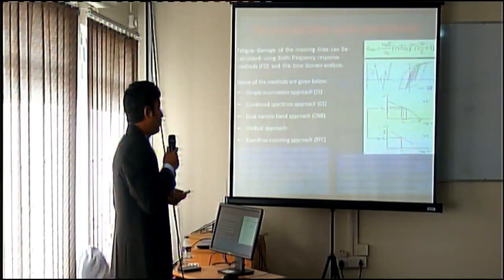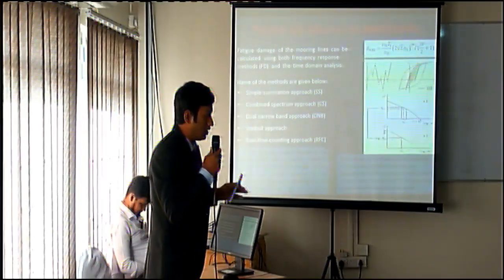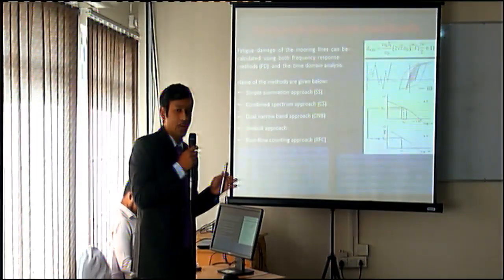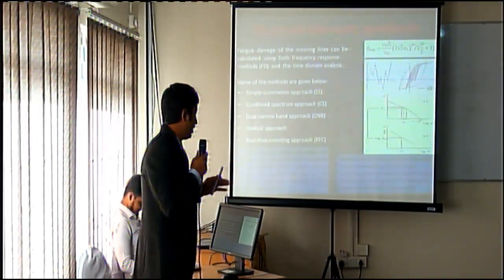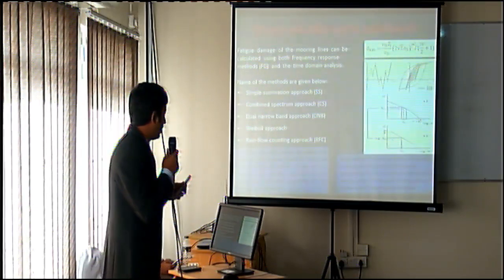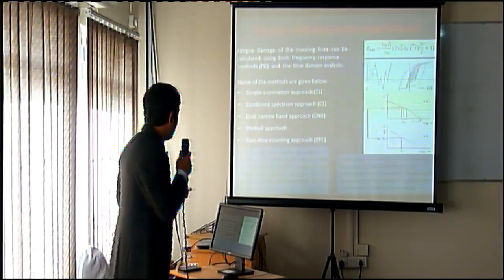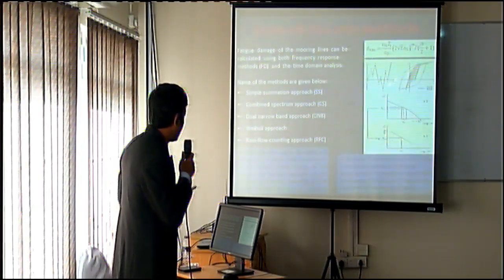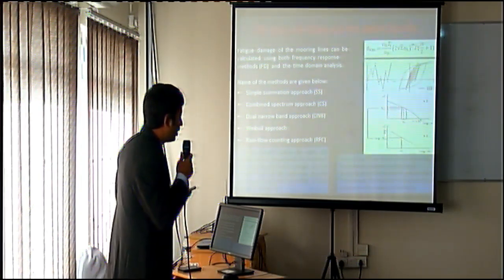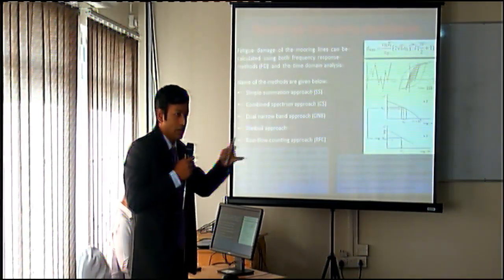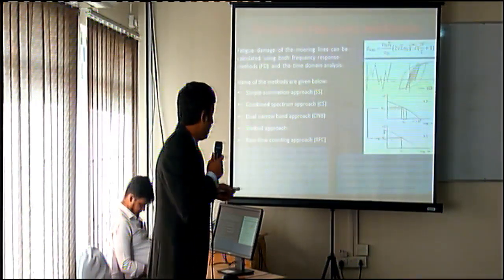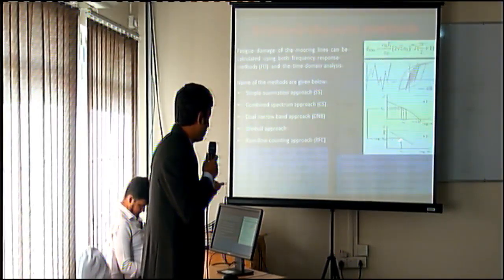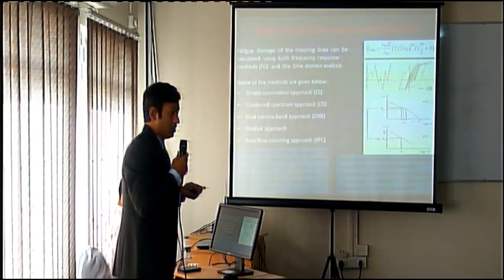That means you need to calculate the time series, and you need to calculate the fatigue levels of the time series for every cycle. For example, the rainflow counting method can count all the cycles involved with the wave loading or other types of loading on the vessel. For each cycle, you need to calculate the damage, and then you will finally get the total damage.